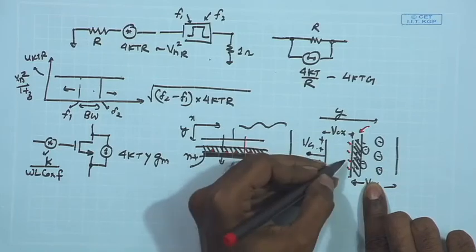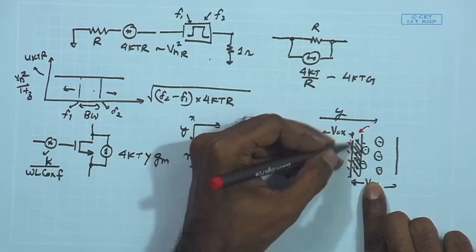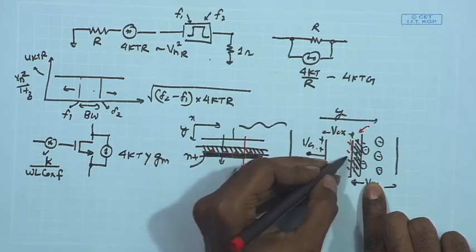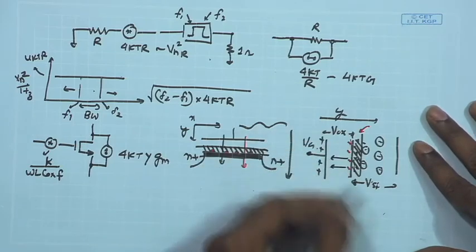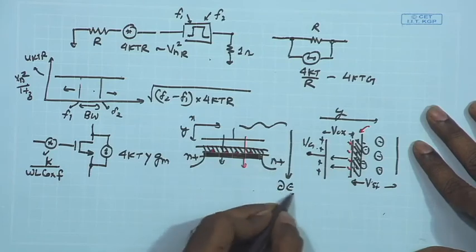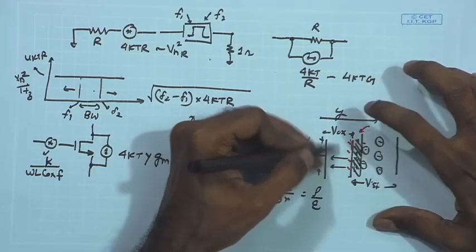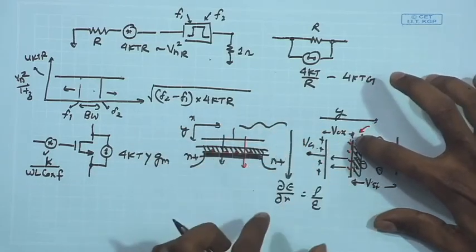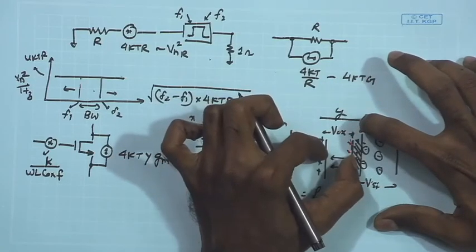And in order to look at the COX dependence, say the random charges you have trapped lie close to the interface. We have an effective electric field produced by these charges, which is balanced by the positive charges on the gate. Gauss law tells us the field is rho upon epsilon. In the oxide region you do not have any fixed charges, and therefore whatever charges you have, integrated over this entire distance, give the overall delta V that is required.